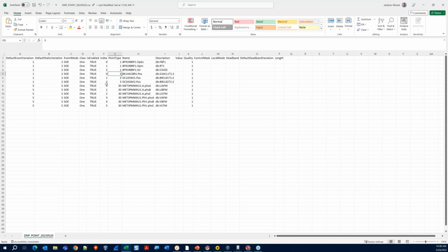Again, we start at 0 and increment, so on and so forth. Now, in this case, we've exported this as a CSV, which I'll be using a little bit later to give you a preview in DTM, but we could imagine a future where you would also export this into a DNP XML device profile, should your gateway support that as an input. To give us a little more insight into what that DNP XML device profile containing that mapping looks like, I'm going to turn it back over to Christoph, who's going to explain that a little bit more.